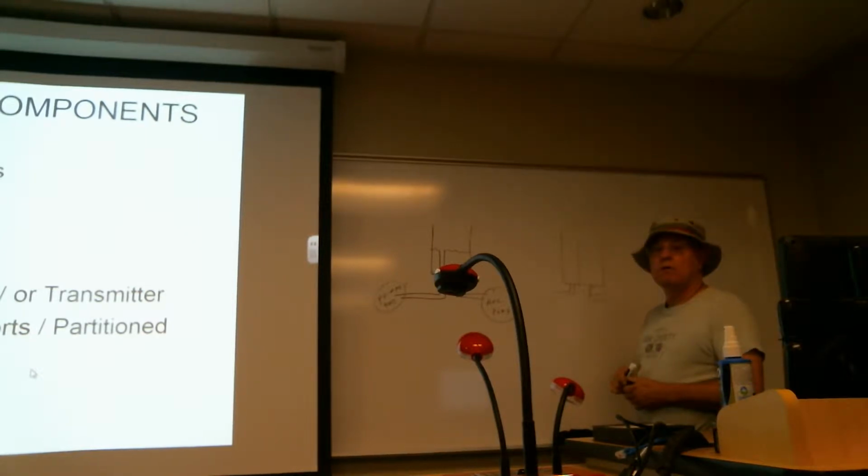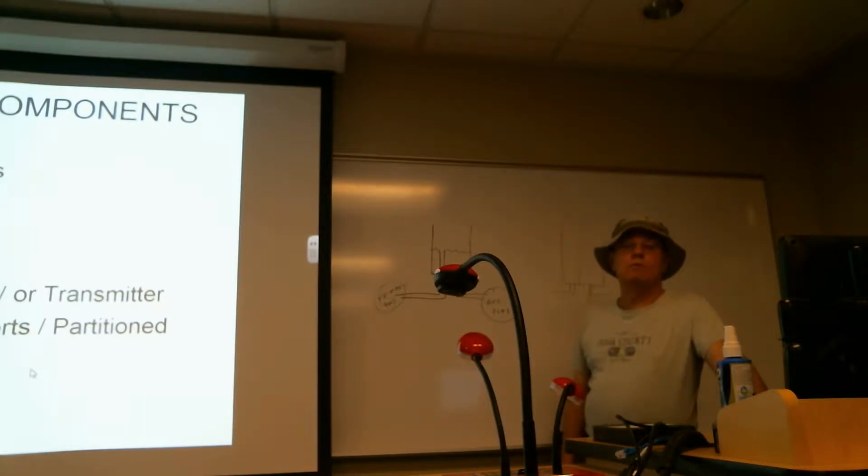Years ago, I remember looking at the reservoir cavity for a brake system in an automobile. Now, they partition the reservoir, but for a specific reason. Why do you suppose they partition the reservoir maybe in that particular reservoir? Why do they do it? How come? So to separate the systems so where one half of the brakes will still work if you end up with a rupture in the other half. Good. Yeah, the idea is it provides for either front brakes or rear brakes in the event that one of the lines should break. So at least it retains the capability to have half of your braking system. So again, kind of the same idea.